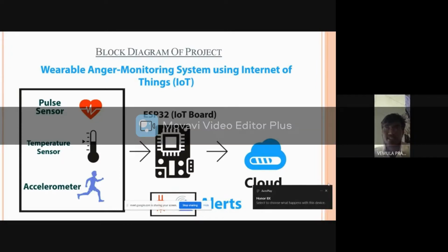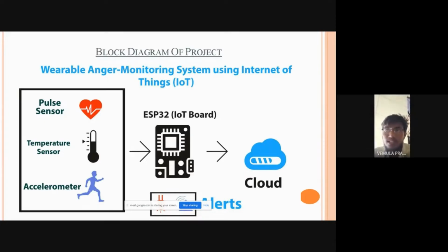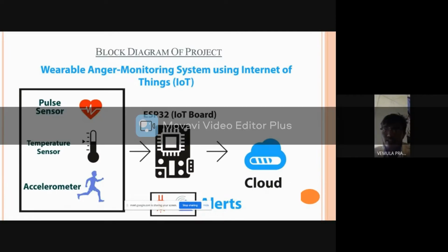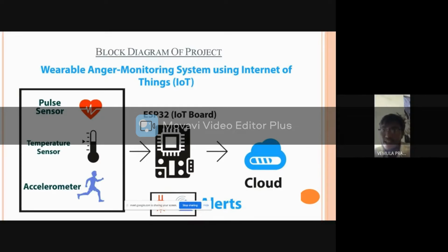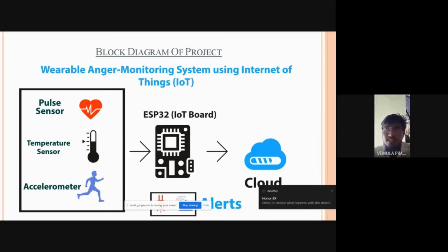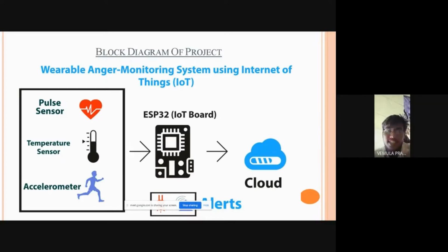In the accelerometer, there are 5 pins. In the circuit diagram, we see X out is the x-axis analog output, Y out is the y-axis analog output, and Z out is the z-axis analog output. The ADXL335 accelerometer provides analog voltage outputs for x, y, z, which are proportional to the acceleration in the x, y, z directions.